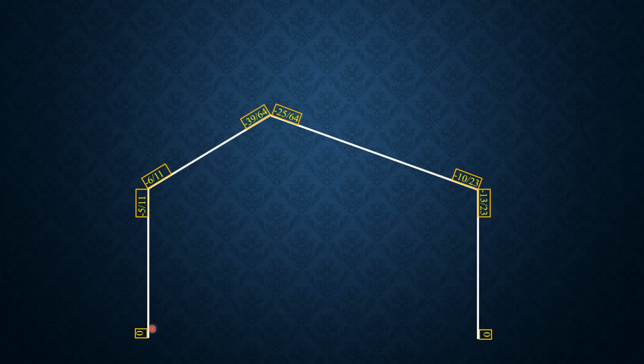So we now apply the side sway moments. Remember, this is negative 30, negative 30. BC is positive 46.286, 46.286. CD is negative 16.483, negative 16.483, and this DE here is 0, 0, side sway moment. So we begin with this zeros, so 0, because the distribution factor is 0.